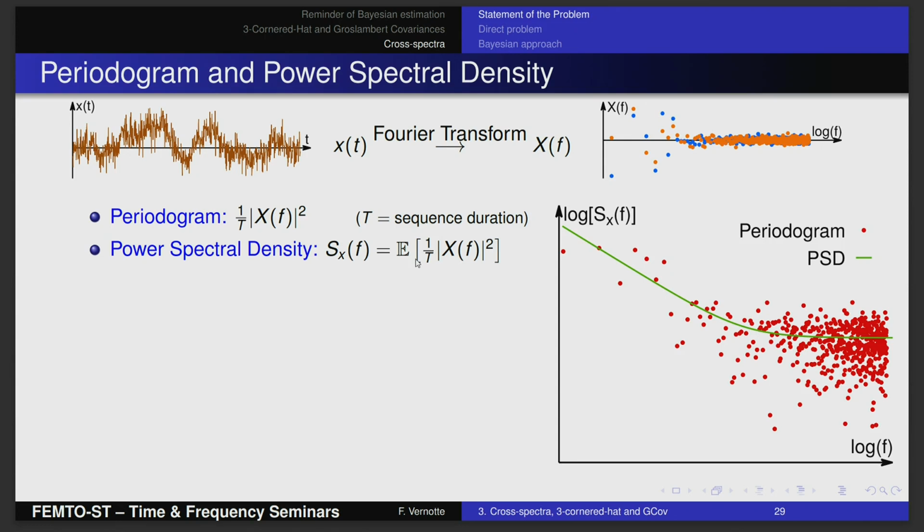But you can also imagine that you have exactly the same experiment, which is duplicated n times. It's a little bit strange, but it's an ensemble average in this case, and you can consider that for 1 time you make the average of all what happens with this equivalent experiment. So what is interesting in this case is that we will have a PSD estimator, which will be something between the periodogram and the PSD, because the PSD, of course, is not accessible, and you will use the periodogram, but you will use a finite average of periodograms. M is the number of periodograms that we will use. We will make an average over M different periodograms.